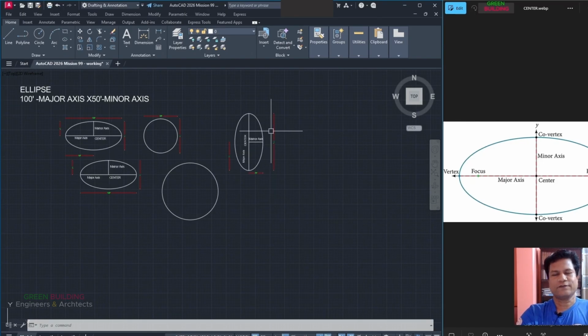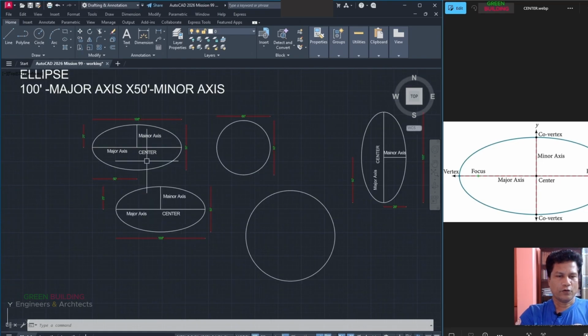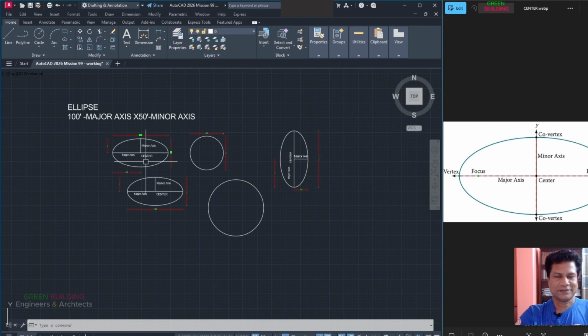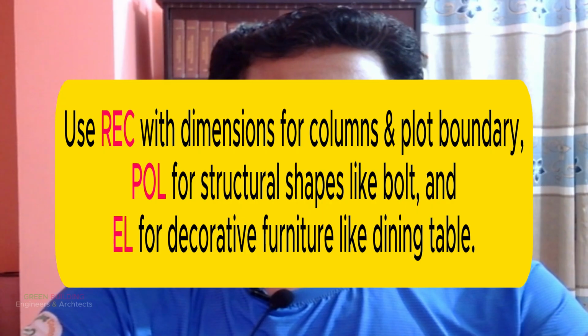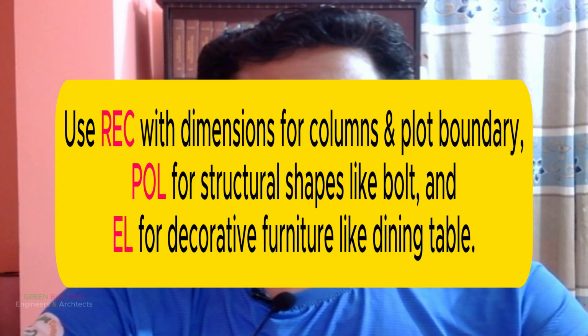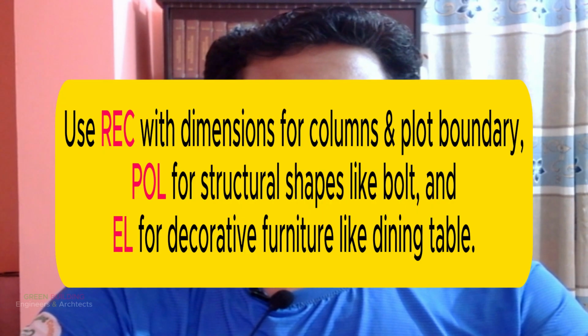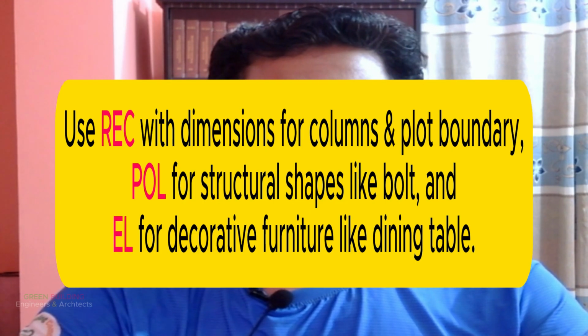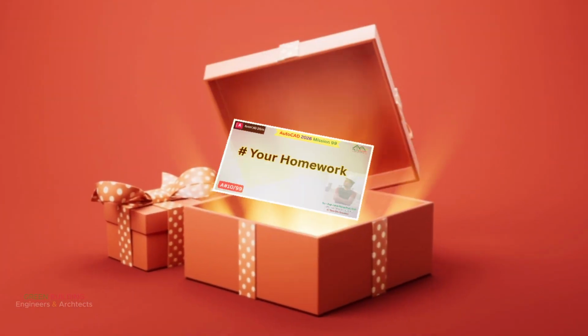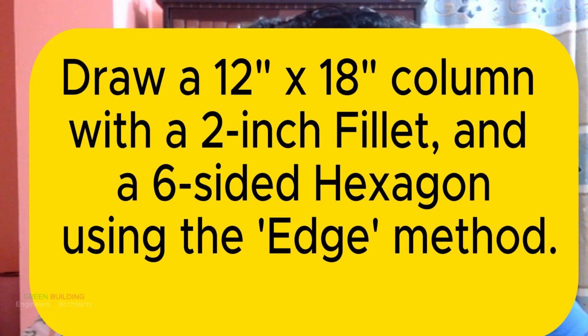Finally, I use this for landscape design or an oval dining table. I hope you learned many things from this lecture. Use REC rectangle with dimensions for columns and floor boundary. POL for polygon for structural shapes like bolt, and EL for ellipse for decorative furniture like a dining table. Your homework: draw a 12-inch by 18-inch column with a 2-inch fillet and a 6-sided hexagon using the edge method.